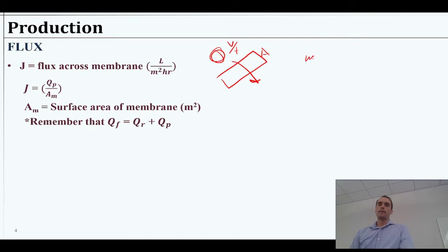So you could write it as cubic meters per square meter per second, for example, or simplify that to meters per second. Or maybe you want to use liters, and that's just more convenient, so you leave it as liters per square meter or per square foot or whatever. The units, although you need to care about them to keep them consistent, as long as you have a flow through that area, you've got a flux. So here we use J to denote flux.